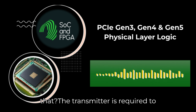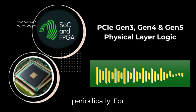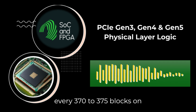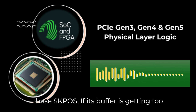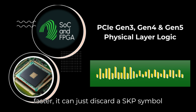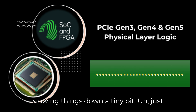The transmitter is required to insert a SKP OS into the data stream periodically. For 128B/130B, it's roughly every 370 to 375 blocks on average. The receiver watches for these SKP OSs. If its buffer is getting too full, meaning the transmitter is slightly faster, it can just discard a SKP symbol from the incoming stream, effectively slowing things down a tiny bit. Ah, just throws one away.